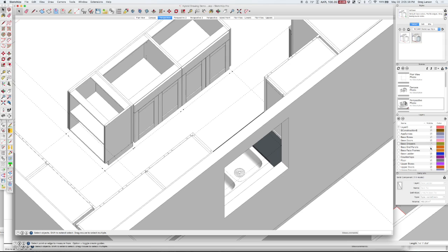Now, if I were to redraw this cabinet here, it would try to redraw it with the parameters that I've got currently set. And I don't want it to do that. So I would have to switch my parameters back to this one. I could have saved them in a special parameter file, which is one way to do it. In the future, CabWriter will remember the parameters you use to draw a cabinet. So when you edit a cabinet or redraw all cabinets, it would redraw it the same way that it did before.